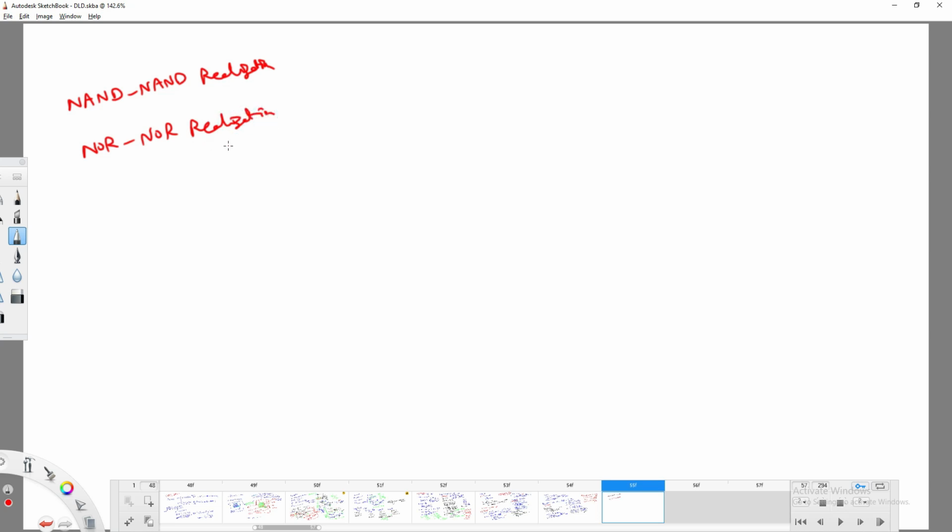If you are going to have NOR-NOR realization, compulsorily your circuit should be in the product of sums. For NAND-NAND realization, the circuit should be in the form of sum of products, right?